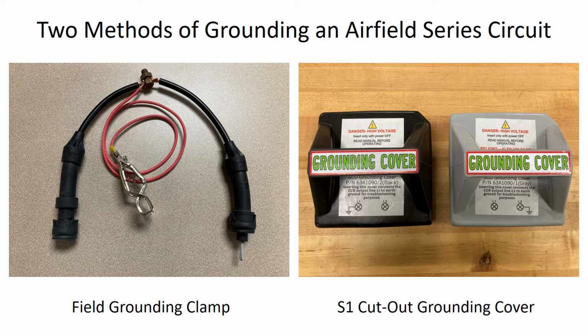And this is a homemade contraption that is simply a male and female connector on a short piece of wire with a grounding lead connected to the center. To install this, you simply open a primary connection at a transformer and plug this into the primary line, and then you clamp it to your ground wire.